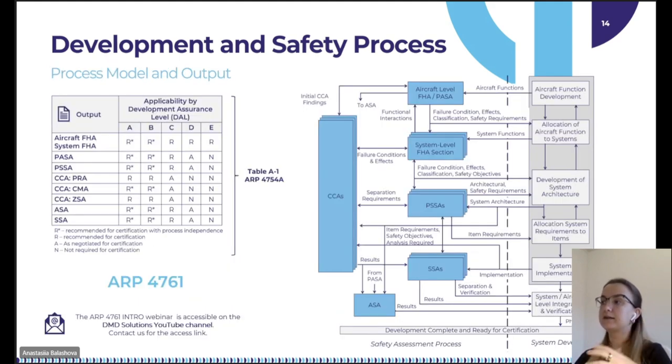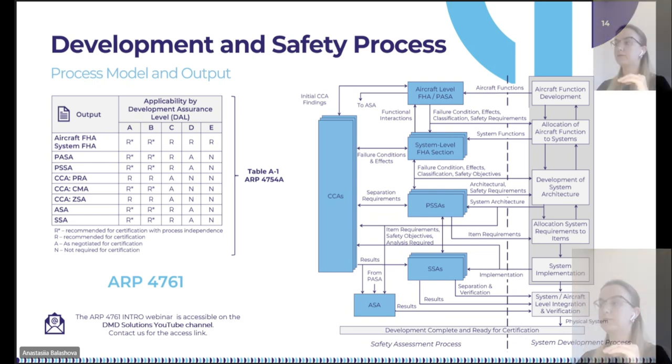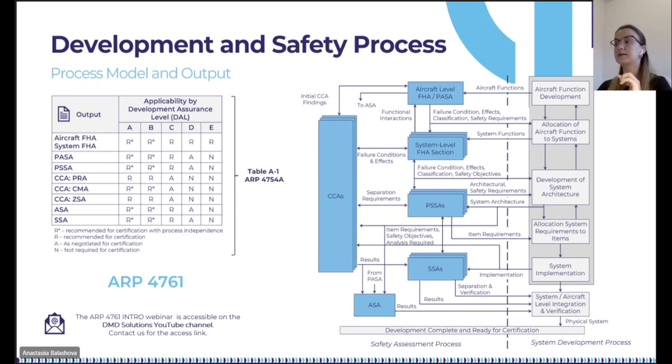The table provides a list of safety analyses that should be released. There is no surprise that the list depends on design assurance level. The ARP4754A requires a safety assessment. The minimum is FHA, which shall be developed even for the DAL E systems. The ARP4754A calls the necessity, and the detailed information of how to perform the safety assessment is presented in ARP4761.